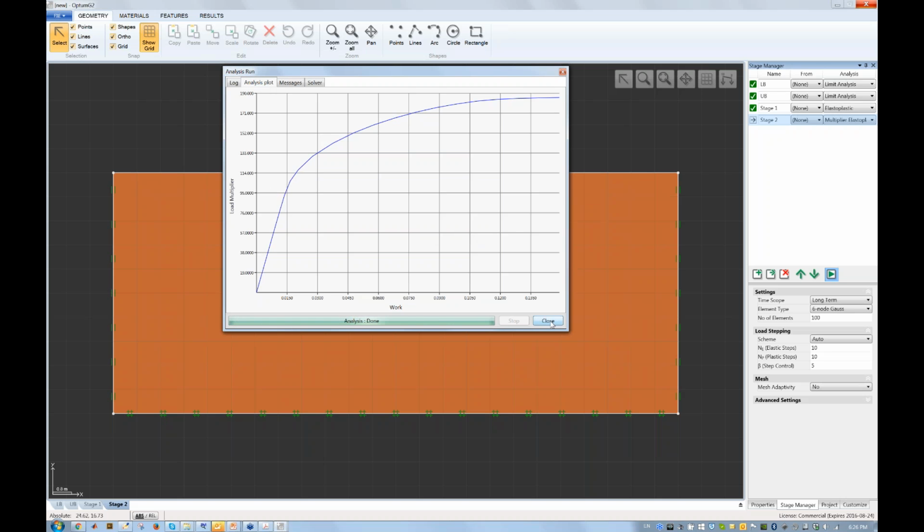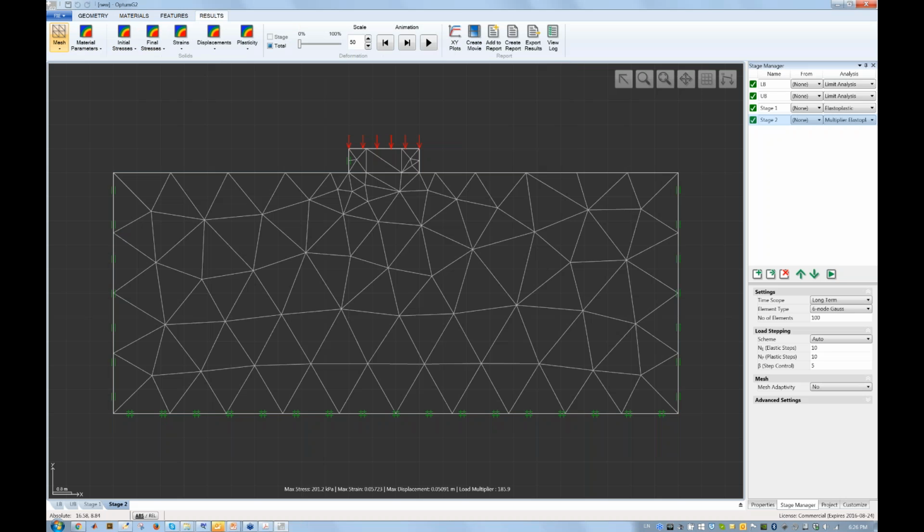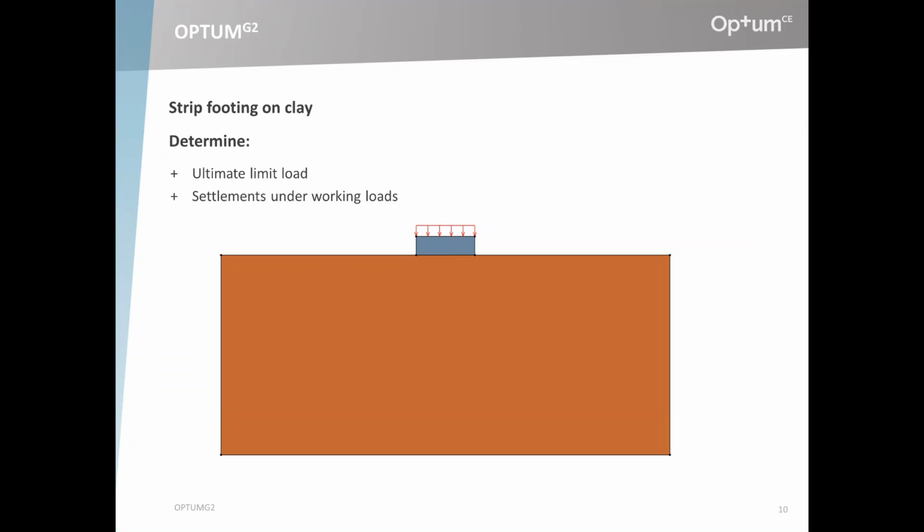That analysis can be conducted as well, even though in many cases it's not strictly necessary. You have the information you need from the two other analyses, the limit analysis and the elastoplastic analysis. And this was for a coarse mesh, I should say. You can of course use as many elements as you like, and you can use mesh adaptivity as well.